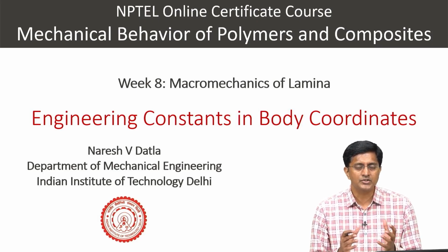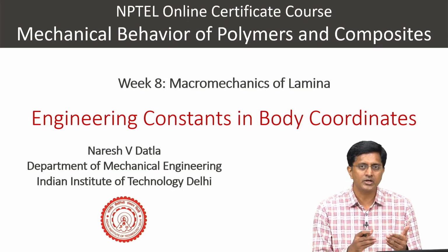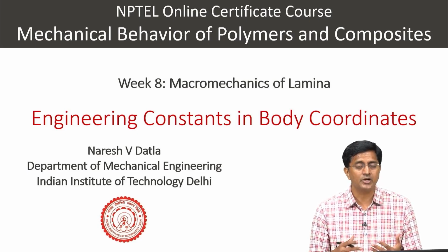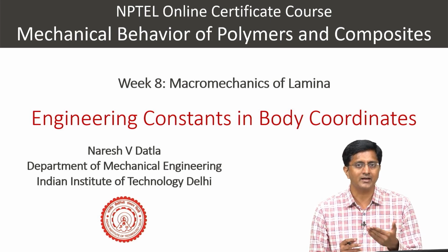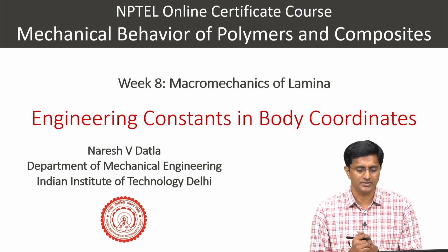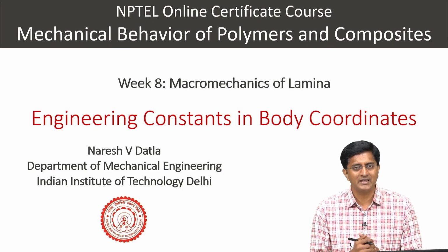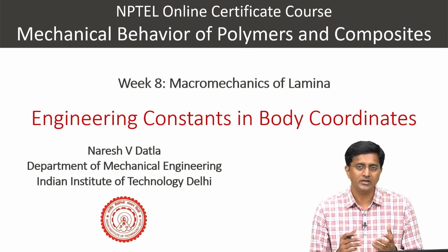But it is not always the case that we are working with perfectly aligned laminates, but as we showed in the last 1 or 2 videos, we do consider these generally orthotropic materials, meaning these laminas are at an angle to the principal directions. Now, once we accept this, that we have an angle theta, how do we define these engineering constants?